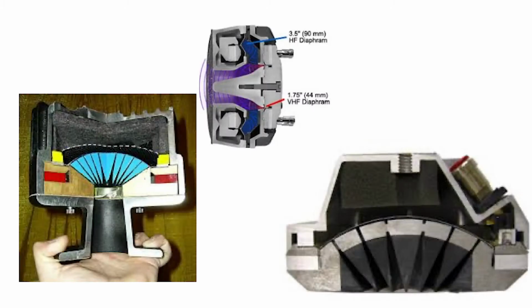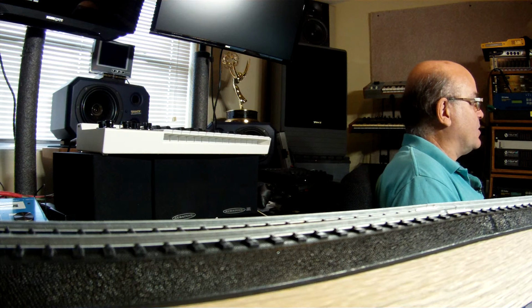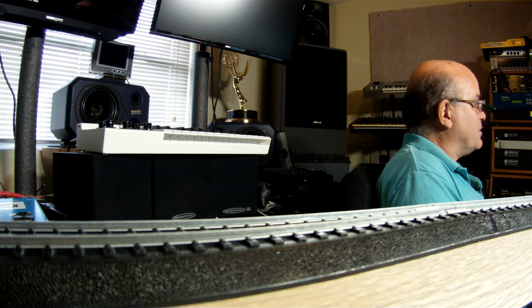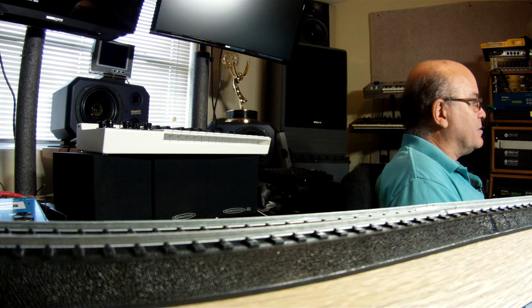A compression driver, when shown in cross-section, looks kind of like a backward speaker. The magnet is on the front of the component, while the diaphragm and voice coil are on the back of the component, as opposed to being on the front like it is on a woofer. There's also a back cover on the assembly. This back cover will typically have a gasket of some type between it and the rest of the assembly. This is where the compression part of the name comes from. This back cover becomes a compression chamber, sort of like the cylinder head in a combustion engine.